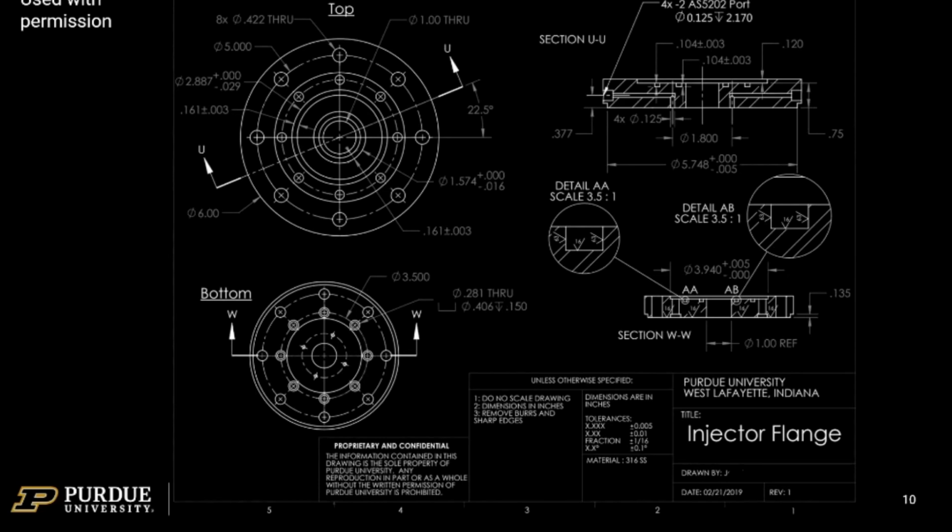And they're going to verify that the physical object contains the same dimensions. And if that's true, the part is said to be to print. The physical manufactured object is the same as the print. And if it's not true, then you can send it back to the machine shop and say this part is not to print. And they can say, well, your print is ambiguous and we did this. Or your print is incomplete. Or, oops, yes, we'll fix that. So it's very important to make sure that your print is achievable and it's fully dimensioned. There isn't extra dimension and there isn't ambiguity.